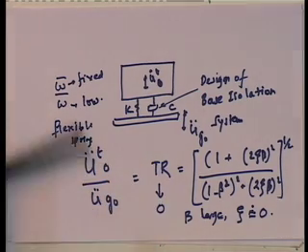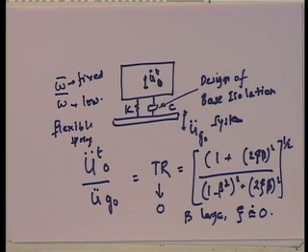You see, the force transmissibility problem and the base isolation problem are identical. Okay? And therefore, both of them essentially are looking at, if you want to design an ideal force transmission to be 0 or base to be completely isolated, in other words, acceleration transmitted from the ground to the equipment or force from the equipment to the ground, both of them essentially require a flexible system.